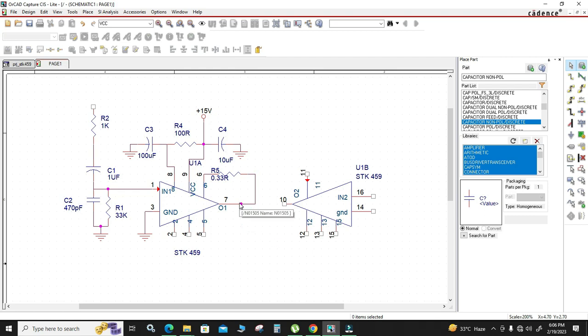One smaller line means that the 7th pin is joined with a small portion of wire here, so we could find it. Then we delete this 7th line first, click here and delete, and one small portion also exists here, which is also deleted. Then press the wire button, select it and join.